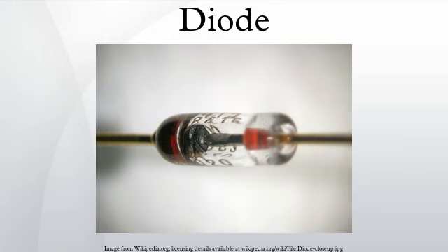A typical example is the 1N914. Snap-off or step recovery diodes. The term step recovery relates to the form of the reverse recovery characteristic of these devices. After a forward current has been passing in an SRD and the current is interrupted or reversed, the reverse conduction will cease very abruptly. SRDs can, therefore, provide very fast voltage transitions by the very sudden disappearance of the charge